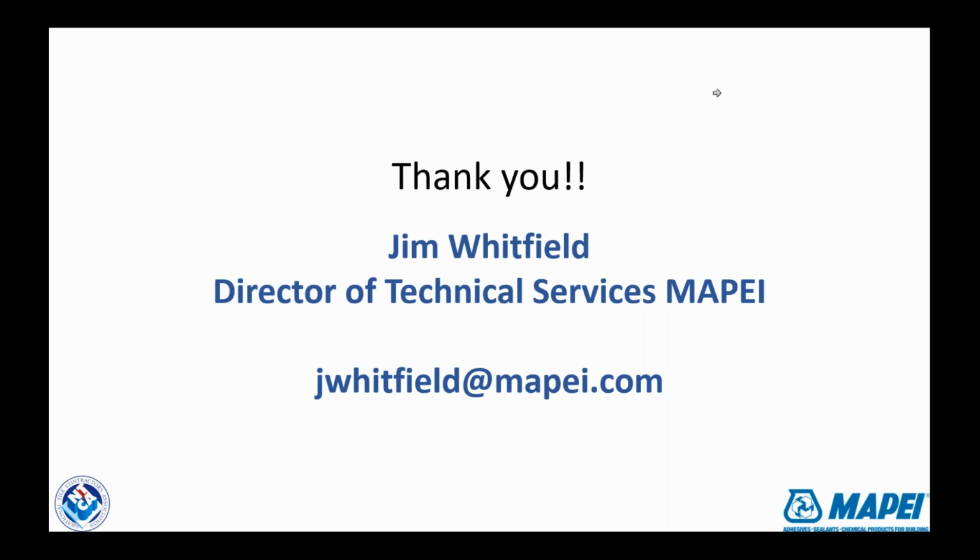A lot of your expansion or movement joints end up being a little wider than a grout joint, right? That's part of what we deal with in regular tile, not just GPTP. And again, that comes down to the architect and the designer. It's the tile contractors' problem, but it's not really their decision. They're not the ones who should be designing it. Exactly. That should be done by the design professional.